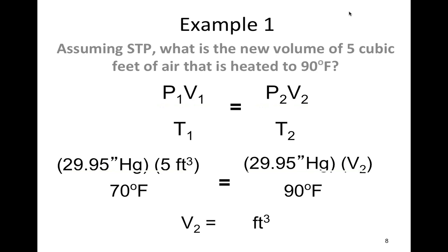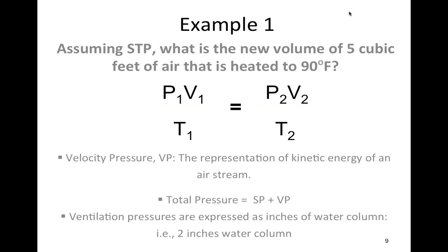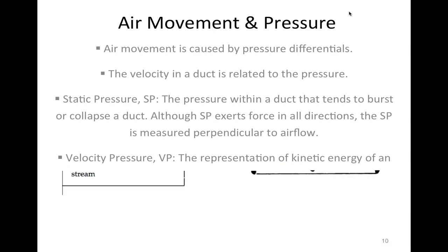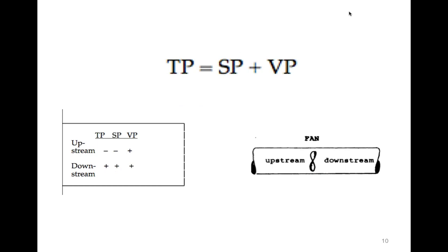And we can use this formula very directly to determine, well, in state 1, if we start out with standard temperature and pressure, and we have 1 liter of air at atmospheric pressure, 14.7 pounds, and it happens to be 20 degrees centigrade, and now we increase that temperature to 40 degrees, we know it's going to affect the top half of that formula. We can actually use this equation to calculate how it affects the pressure or the volume. We have an example of that we're going to play with. I'm not going to actually run it through here. We'll do it when we get to our examples.